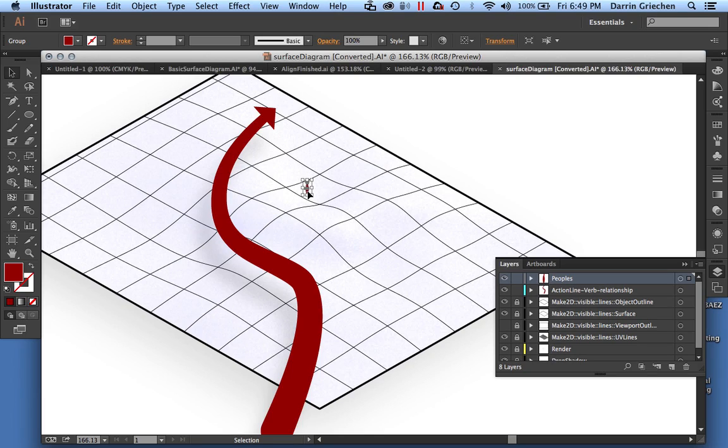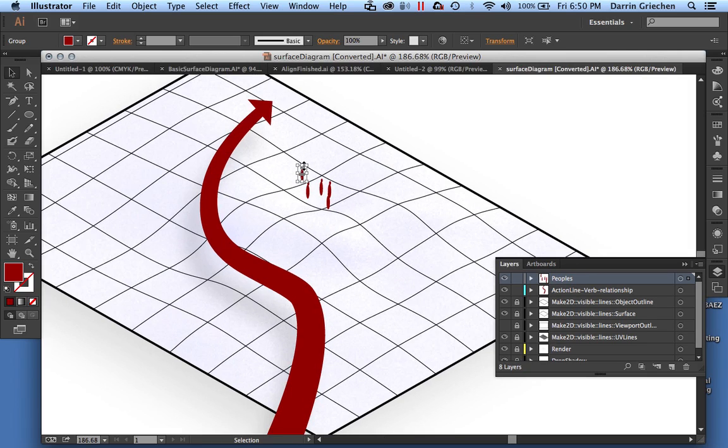And then if I want to copy them, you want to make sure that you don't get these kind of arrows. You just want the simple arrow. If you hold down the Alt key and click and drag, you can create copies. I'll zoom in here a little bit more.